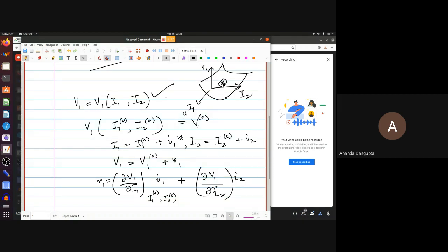In fact, in an actual amplifier application in transistors, you would have to set your quiescent point currents and voltages just right, so that when you change the currents a small amount from the quiescent point value, the voltages will change in proportion. Basically what you want is an amplified version of your input to occur at the output, but you don't want a distorted version. You don't want something which does not look like your input signal at all. So you want a proportionality. For that, you may have to choose your quiescent point value carefully. And that is how this system is actually used most of the time.